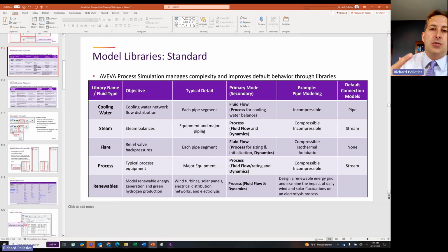So everything from your pressure safety relief valves on all of your different equipment, all the way to the outlet flare stack. These are going to be typically large piping systems where a bunch of pipes from the different safety relief valves are going to be either coming together at different points and going towards a flare, or even within that network, there could be distribution and recycles and other things that make the flow a little bit more complex.